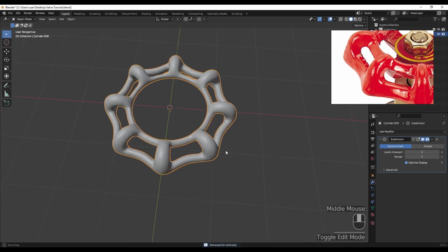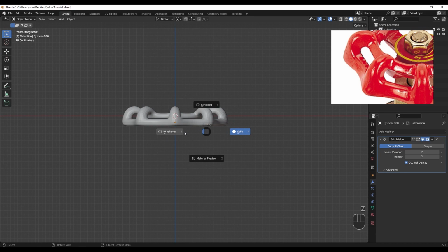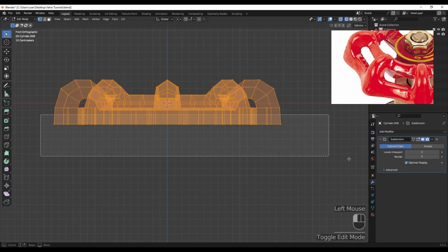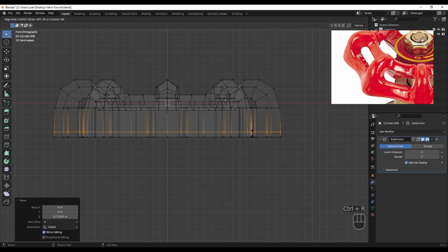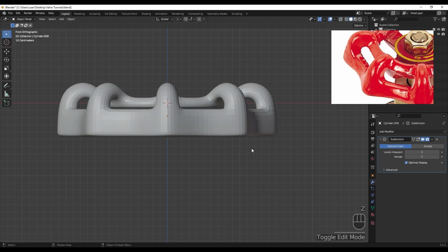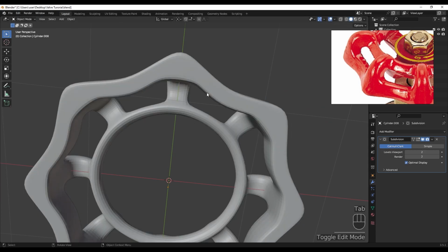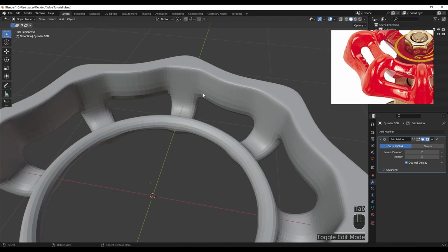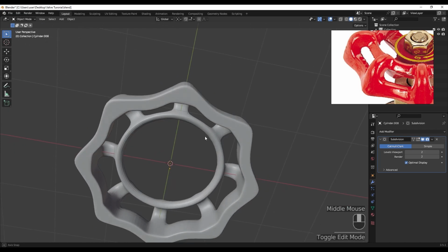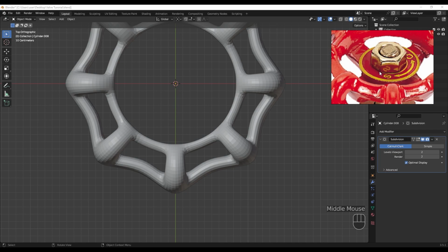Now, if you go back to your object mode, this is your result. Now I'm going to go to edit mode and I'm going to select these vertices. I'm going to put them down here and adding an edge loop like so, and also here, and maybe here, and also inside of this, something like so. All right, now we need to add a cylinder inside.